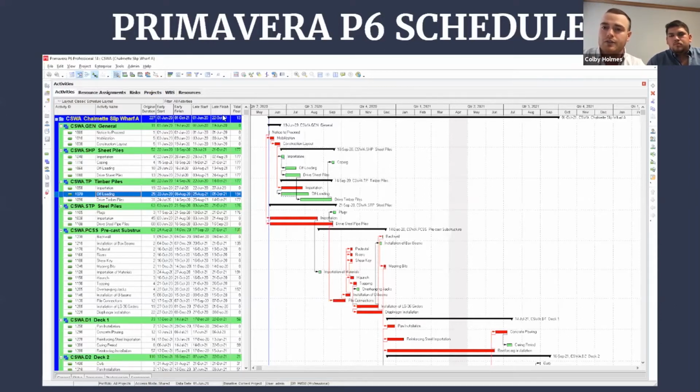On the left side of your screen, you see these red bars. Those red bars are the critical activities. Those are things that cannot really be pushed back, hardly any, if you want to finish by the date that we gave you. And those green bars are not-so-critical activities. So say you have something coming up that you need to get done before a day that you've looked at the Weather Channel and you know it's going to rain. Those are the things you can push back, and you'd rather push back those green things a couple of days maybe than the red activities.